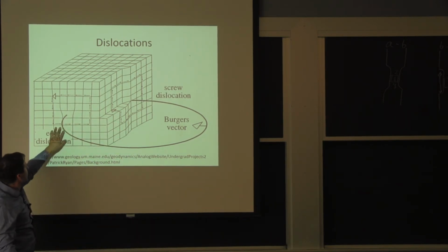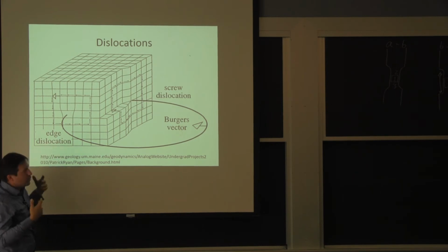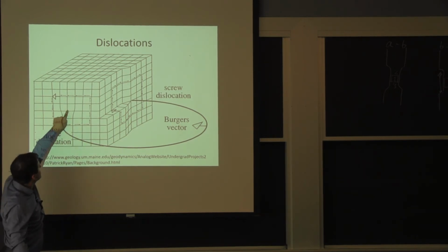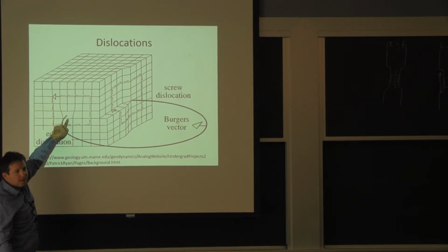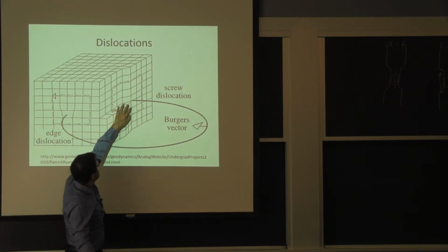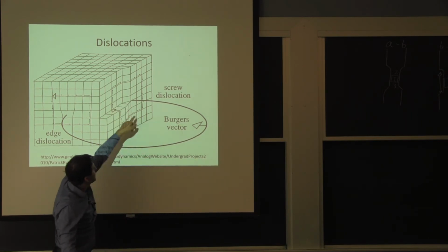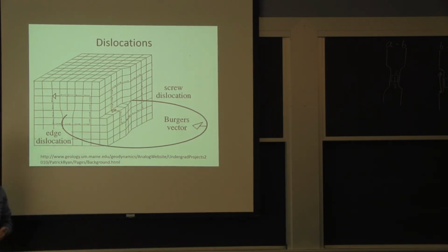I'm getting a full loop of dislocation. I had nothing to begin with. And then all of a sudden, I have zones of tension and compression. Like over here, I have an extra atom, and I have one atom less down below. If I'm looking here, it's twisted. So that's the screw dislocation. But it really came out of nothing.